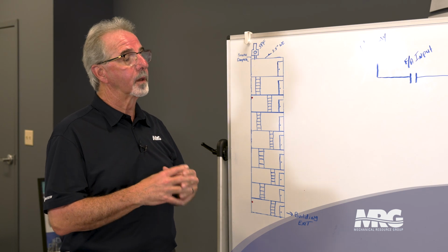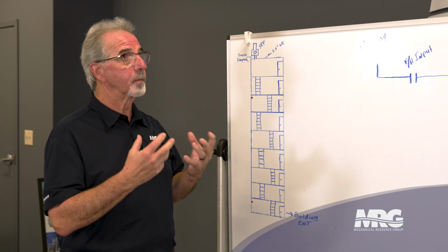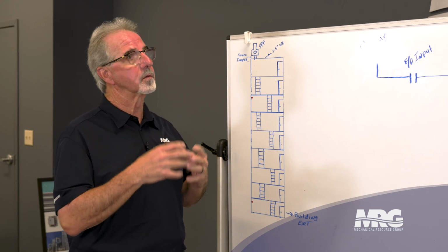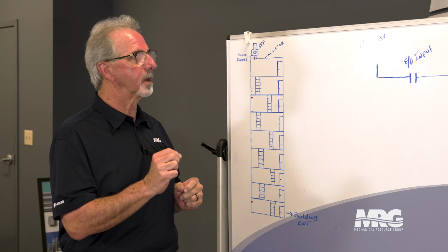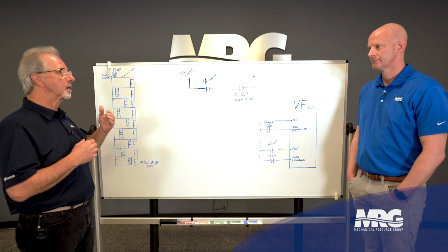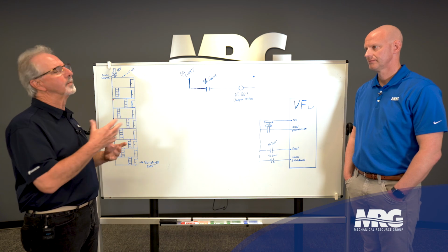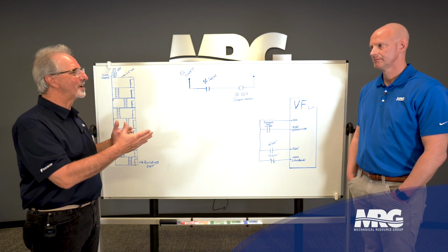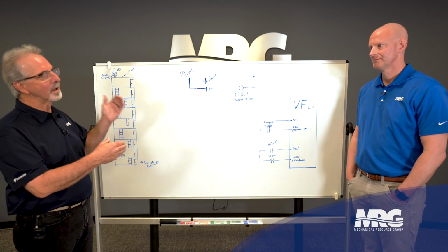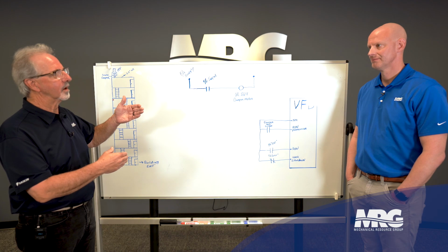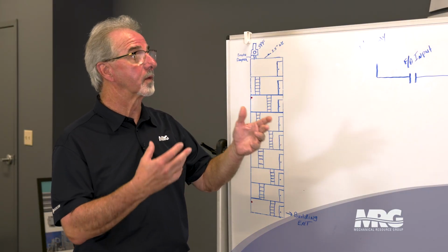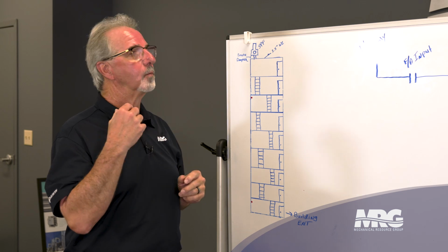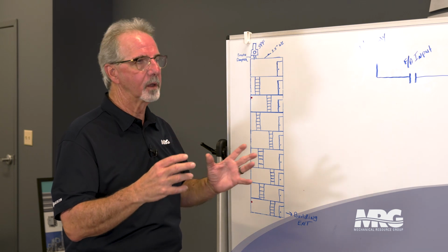my first question is, okay, do you have a damper end switch? And if he says yes, then I know that that's going to be my run permissive, not my run command. So I'm going to be looking for, on most drives, it's safety interlock or whatever. I can send it a run command, but the drive's not going to run. Okay. Then when I get that contact closure, that's a run permissive. That says, okay, go ahead, and when you get that command, you can go ahead and start running.